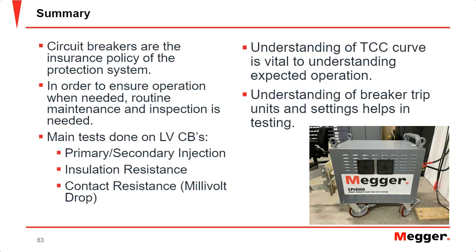So in summary, these breakers are the insurance policy of your protection system. If anything goes wrong, there's a high fault current, you want to protect your most critical assets, and that's what the breaker is designed to do. So you want to make sure that it operates when needed. And to do that, you have to perform routine maintenance and make sure you inspect it accordingly. Main tests done on low voltage circuit breakers, again, are your primary injection, your insulation resistance, and your contact resistance.